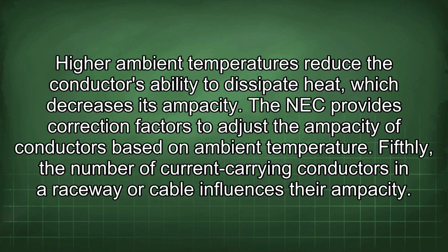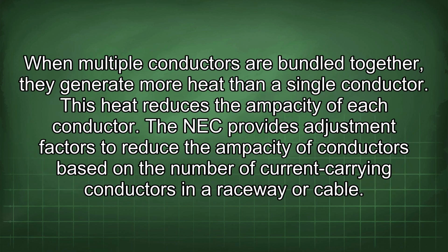Fifthly, the number of current-carrying conductors in a raceway or cable influences their ampacity. When multiple conductors are bundled together, they generate more heat than a single conductor. This heat reduces the ampacity of each conductor. The NEC provides adjustment factors to reduce the ampacity of conductors based on the number of current-carrying conductors in a raceway or cable.